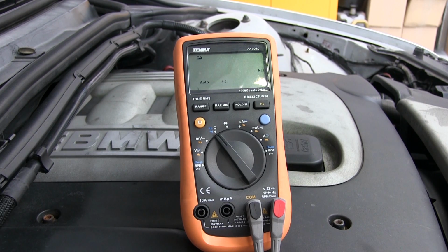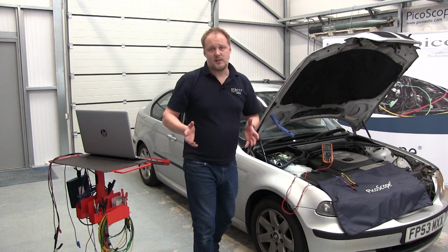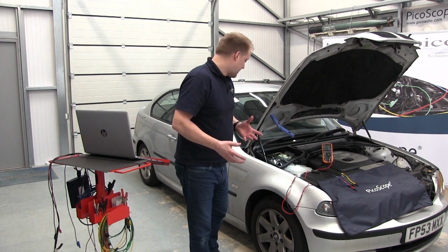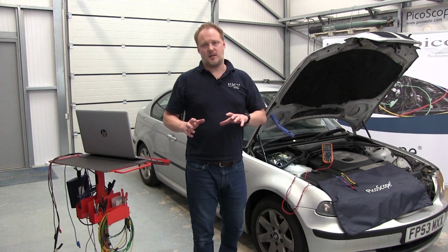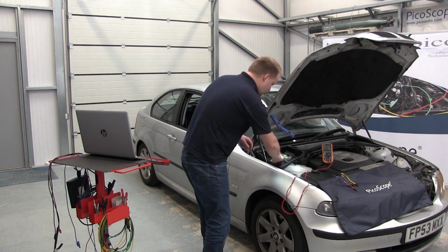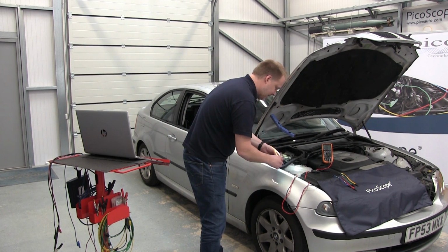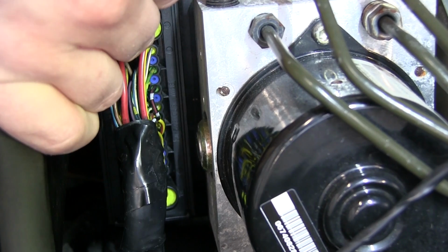Waiting for it. There we go. And we're at 61.78 ohms there. So that's lovely. That's exactly what we expect, and that's good. Say it wasn't good, what you weren't expecting, then the next thing we could look at is the termination resistors at each end. So to do that, if we take out the backpinning probes, we can disconnect the ABS module,